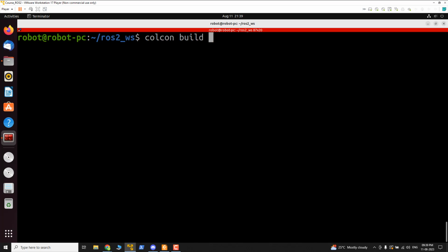If you are only working with C++, colcon build is enough. But if you are working with Python as well, I prefer you to use symlink install. The symlink mainly helps you change the Python file from the src folder, so even if you change the Python code, you can run it. Maybe I can explain it after the build command, so you will get an idea.